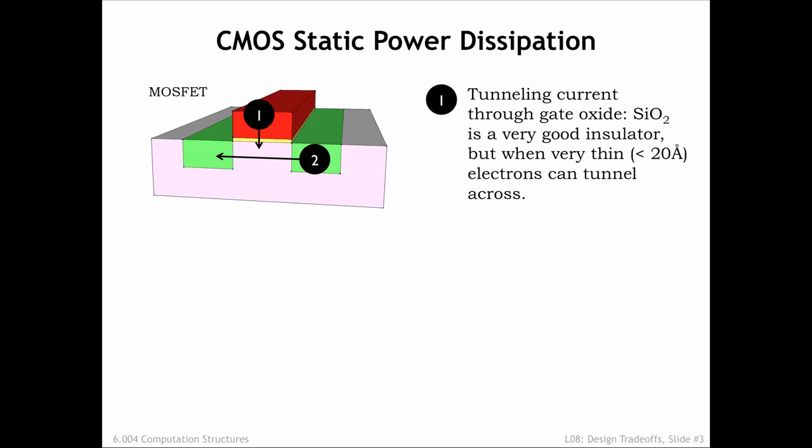The thinner insulating layer means stronger electrical fields that cause a deeper inversion layer that leads to NFETs that carry more current, producing faster gate speeds. Unfortunately, the layers are now thin enough that electrons can tunnel through the insulator, creating a small flow of current from the gate to the substrate. With billions of NFETs in a single circuit, even tiny currents can add up to non-negligible power drain.